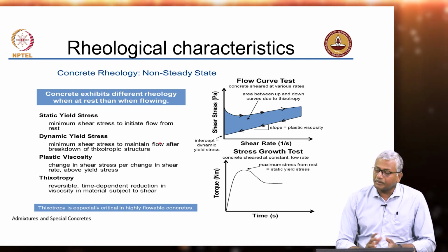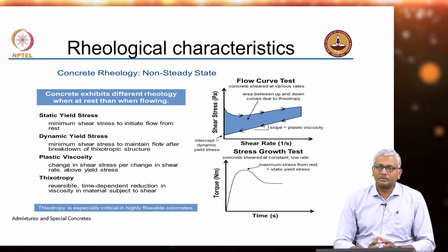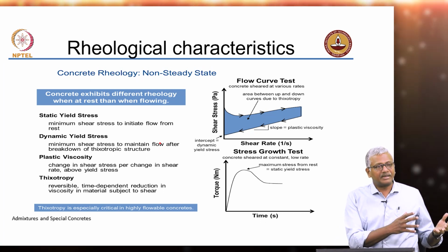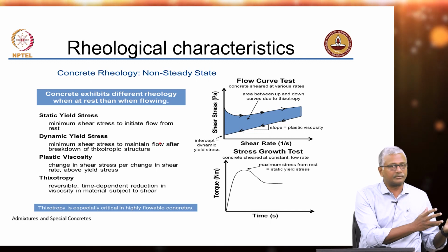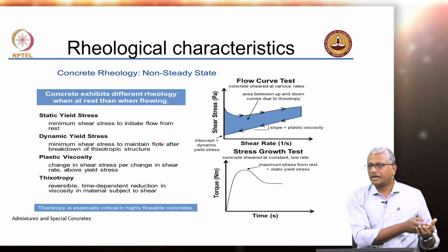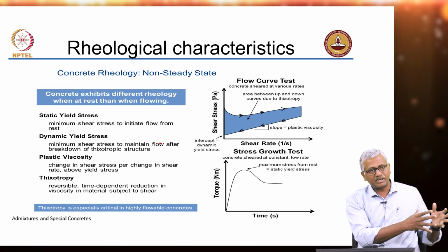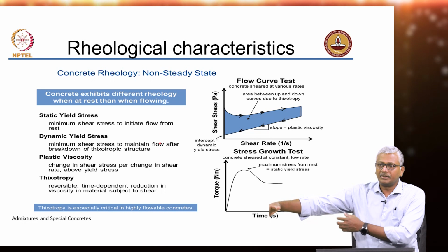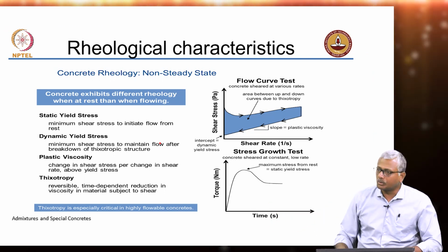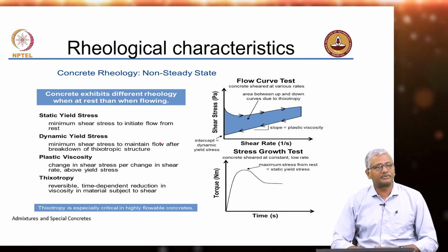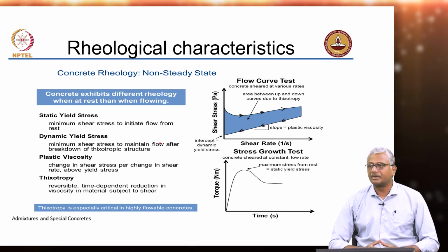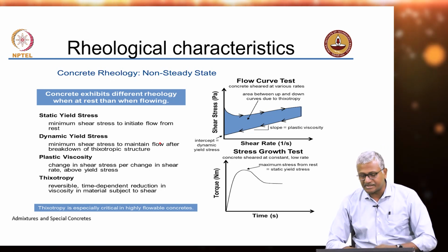Right. So, taking a slightly different approach to understanding this behavior, we start from a period where the entire system is being mixed for the first time. It is almost like from rest you are starting to agitate, right, and then you allow time for the concrete to be delivered to the job site. At the job site you increase the shear again and cause it to start flowing out, right. So, there are different types of shearing that you are doing in this entire process. Because of this, you need to start looking at various segments of this rheology.